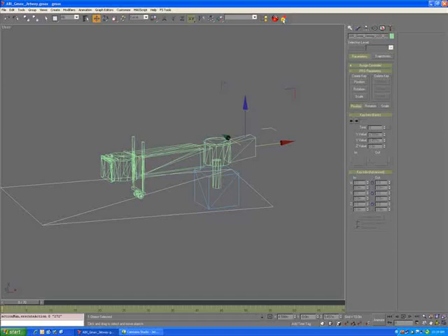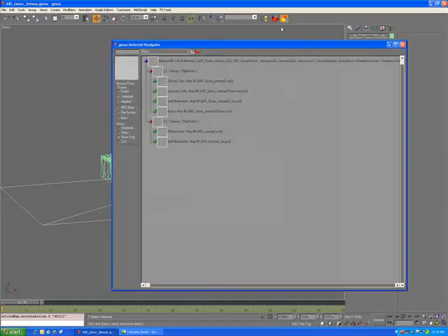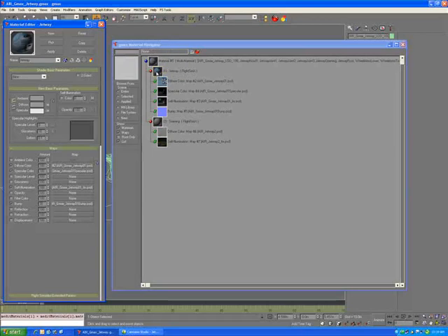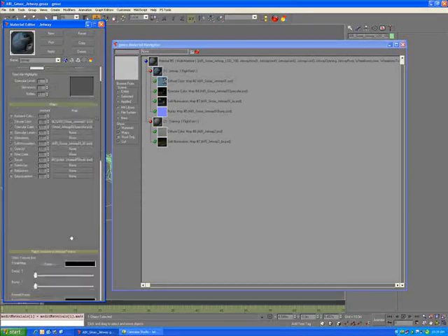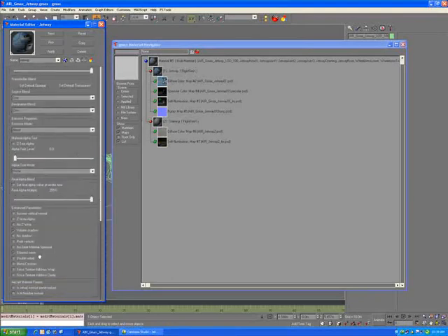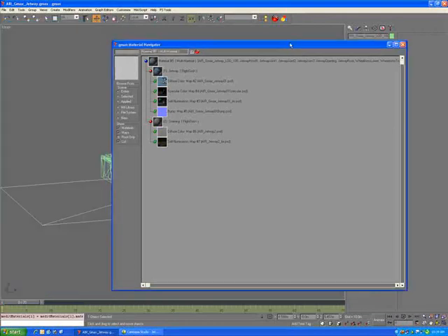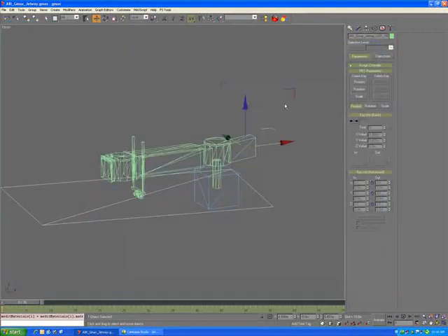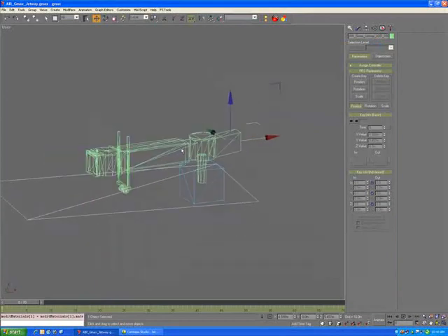so that it takes one draw call to render. So the first thing to do is to verify that your material is actually a skinned material. As you'll see, I've got the standard Jetway, specular, normal map, night texture, etc. And if you scroll all the way to the bottom, you'll see that I've got a skinned mesh selected here, and that will guarantee that when all the bones and the rig is inside it, it will skin up and act as a Jetway, but that will also take only a single draw call.